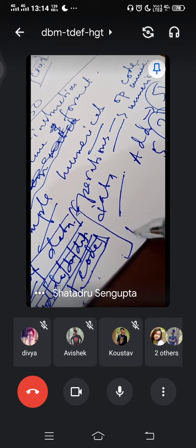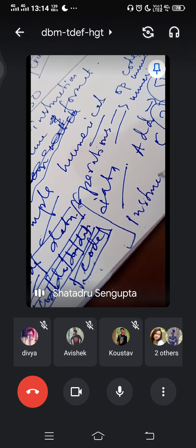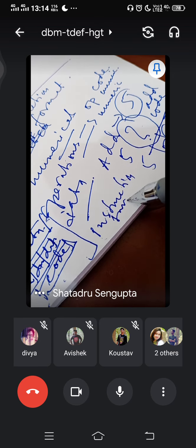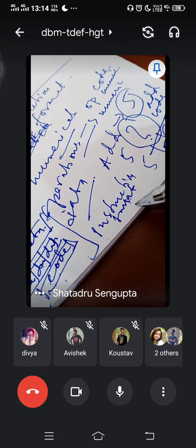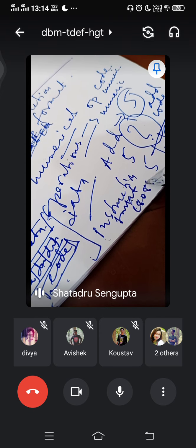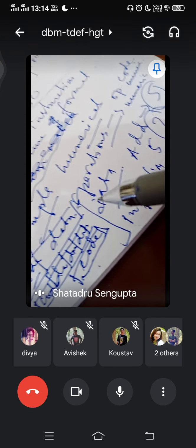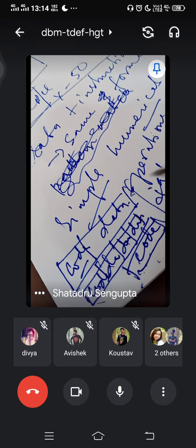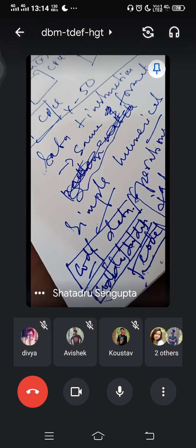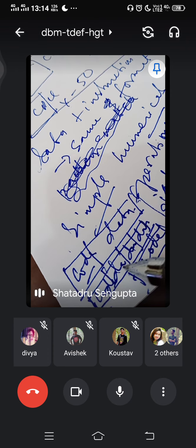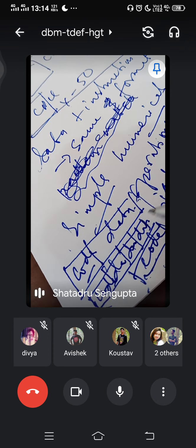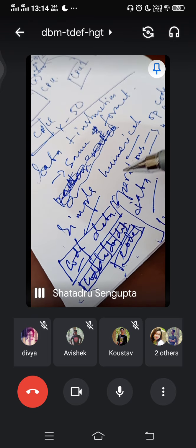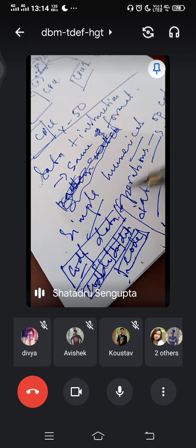The instruction format can be specific. This is instruction format, an example that I've given you from 8085 Intel microprocessors. These are byte length codes. Each of these boxes that you see is a byte each. This is an 8085 instruction format. There are different other formats available with different other CPUs, different other designs.